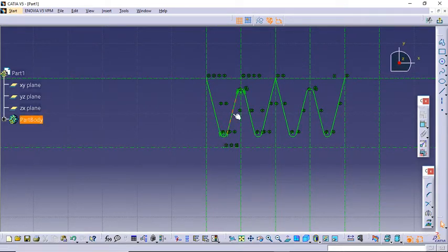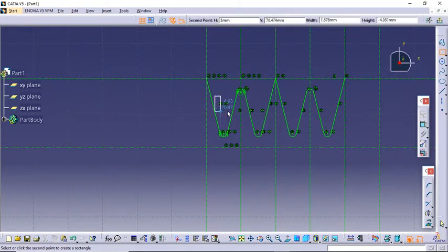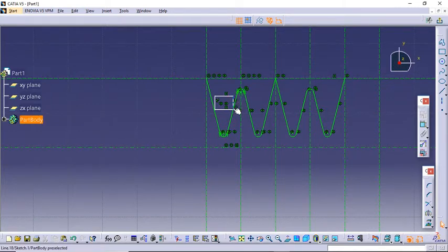These are the specifications which we are taking here. These are really important, they depend upon the size of the belt and the amount of power you want to transmit, because what it does is hold the belt here. Suppose here is a belt, so what this V section is doing is providing contact from 3 sides, one here, maybe one from here, and it depends upon the belt. So it is providing a wedging action.